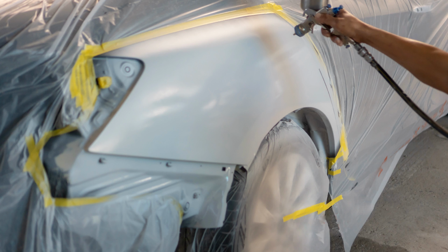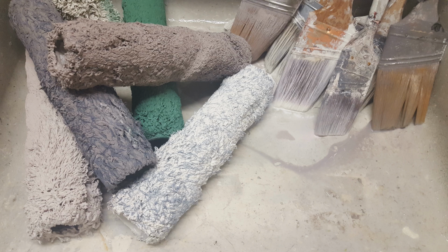You should always wash spray guns in a self-contained cleaner. You can recycle the cleaning solution, but should never discharge waste from spray guns to the sewer or storm drain. Used paint, exhaust filters, residue, and cleaning solvents may be hazardous. They should be handled, stored, and disposed of as a hazardous waste. Never rinse brushes or containers into a street, storm drain, or water body.